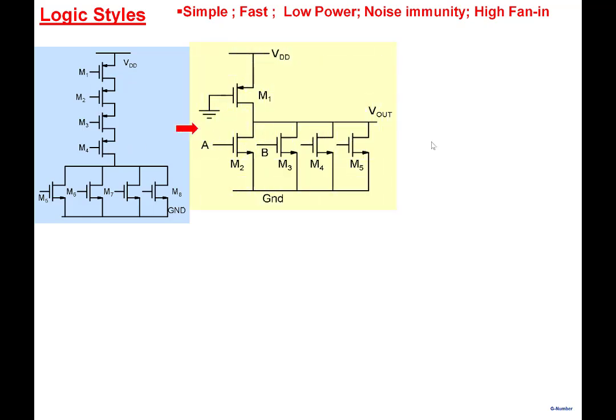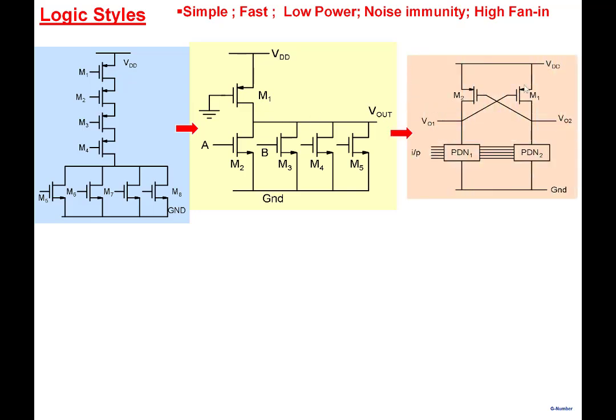And in the process, let me just summarize. This is the main bread and butter, as people say, of CMOS, a fully complementary CMOS. Whatever you see here is complemented in this particular part, and it is the dominant logic. But we have seen that it has problems. Now you should be able to recognize that this is a pseudo NMOS logic. What are the problems that this logic solves, and what are the disadvantages that it has? In an attempt to overcome some of the disadvantages, we end up getting this particular gate here. This was the differential cascode switch logic. It solves some of the problems that you see here. This is one way of addressing some of the problems of this particular logic.